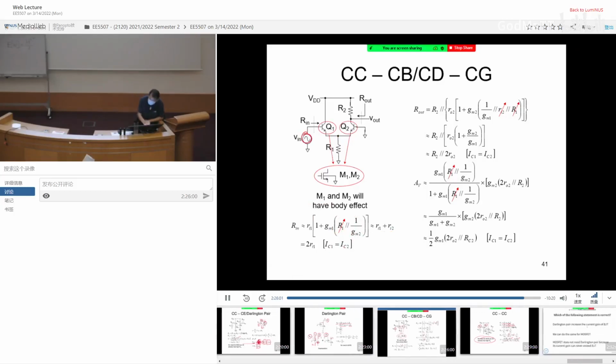This is an AC source, so in DC it is a short circuit. So this is also ground. This is also ground. So the VBE here and the VBE here are identical. Agree? If VBE is identical, the current is identical. So I come to the conclusion IC1 equals IC2. Okay? So therefore Ri1 and Ri2 equal each other.